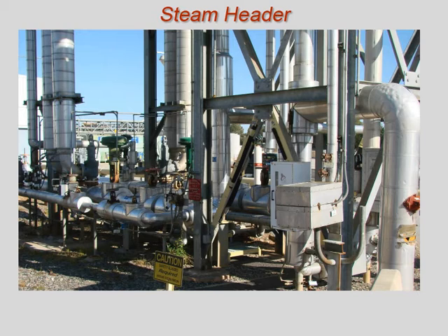A steam header is simply a series of piping and valves. They are used to transport steam produced in the steam generator to be distributed to various components for use. Steam headers incorporate reducing stations to provide the correct steam pressure to systems and components. Steam headers will also include control valves, drain valves, steam traps, and manual valves used for system startup and isolation.